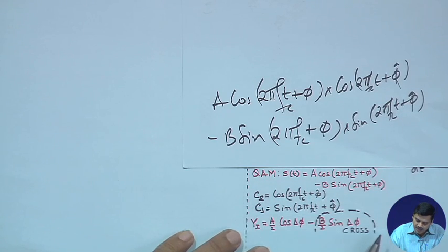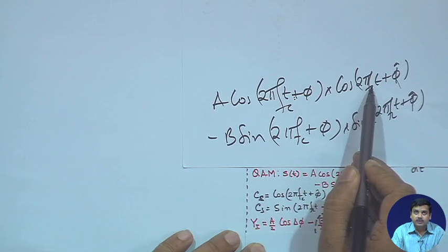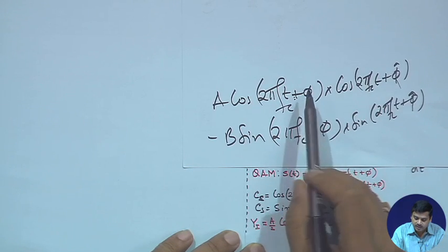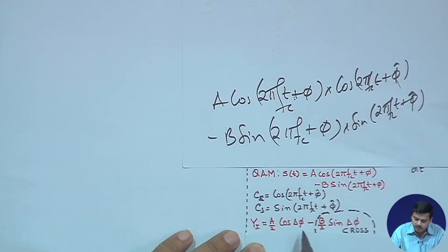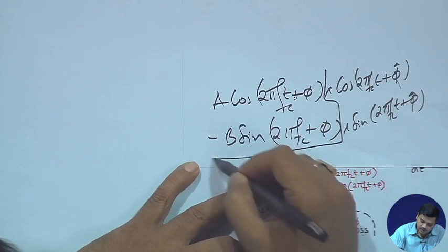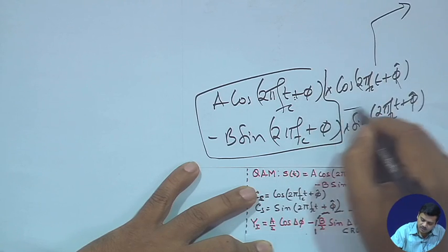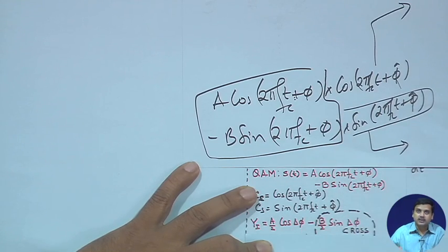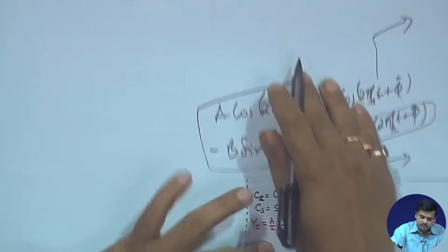So, this is at the end of the multiplication. After multiplication and filtering through a low pass filter, you are left with A cos delta phi, that is what is here, and you are also having B sin delta phi. So, that means you are going to multiply this with cos going to one channel and this with sine going to the other channel, right. So, you have A by 2, that is how the receiver works.